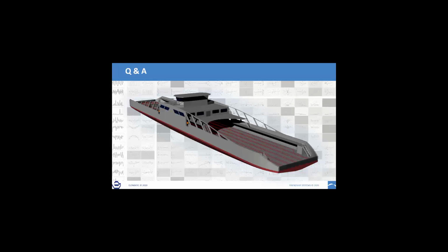Yeah, at least for the approach that I've shown, there are usually two directions to take care of. If I create those surfaces between the flat of bottom and flat of side, I'm usually okay with tangent continuity, because the flow is perpendicular to the direction of the section. So I'm not aiming at more than tangent continuity there.